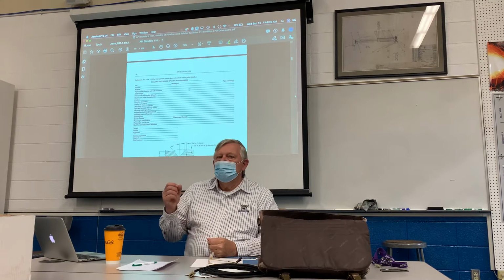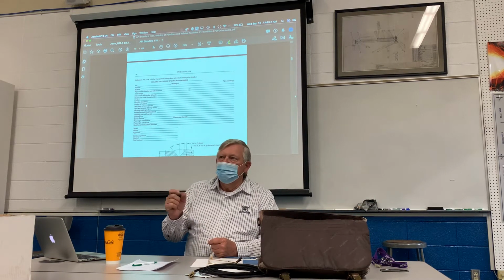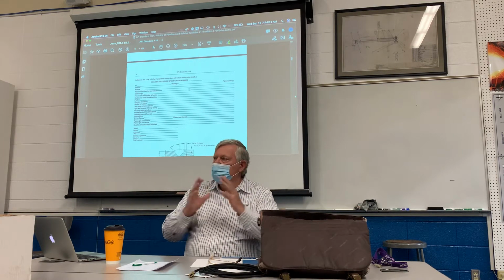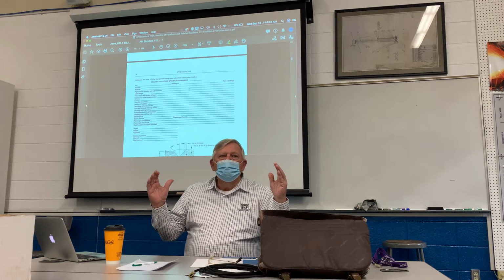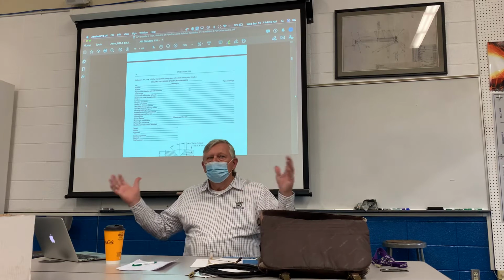Is that limited to just that? No. There are a lot of engineered, specified wall thicknesses. The diameters don't change. They're all standard wall, all standard diameter sizes. But if it's less than 12, it's going to be ID. If it's over 12, it's going to be OD.